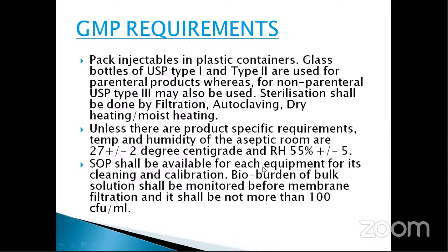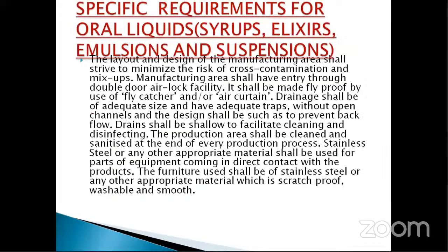And the room temperature is maintained in the aseptic area at 27 plus minus 2 degrees, RH 55% plus minus 5. SOP shall be available. Bioburden of bulk solution should be measured, and the layout and design of the manufacturing area shall be strived to minimize the risk of contamination. Drainage shall be adequate, and in the factory, if you go through the oral liquids, I think today's time is over. Okay, it will be taken the next day.